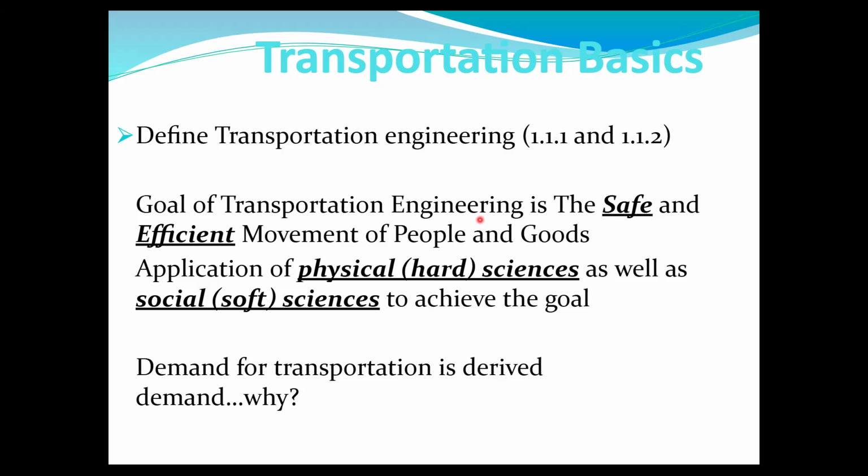Safety and efficiency are twin goals, and we want to achieve both. But when they're in big conflict, we want to prioritize safety, though we don't always do that. In practice, sometimes you'll see people sacrificing safety for efficiency. For example, in my opinion, you want to probably have slower speeds in downtowns, because there might be a lot of pedestrians, and as speed increases, pedestrians are at an increased risk of dying from collisions. So if you want to really prioritize safety, we would probably reduce the speed so much on city streets and not so much on freeways.